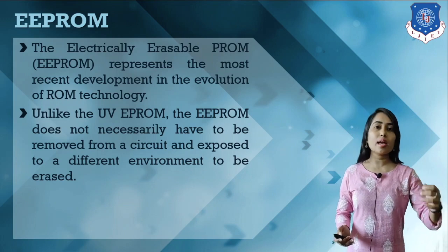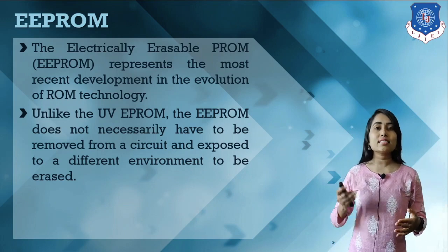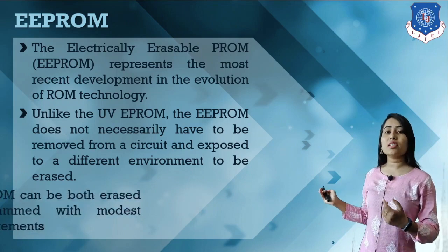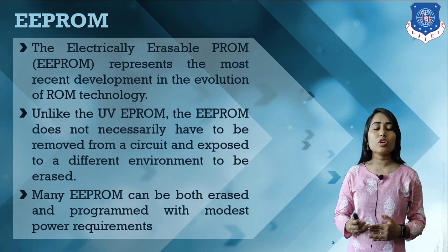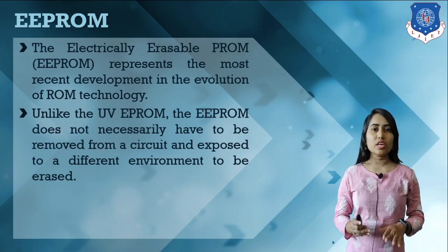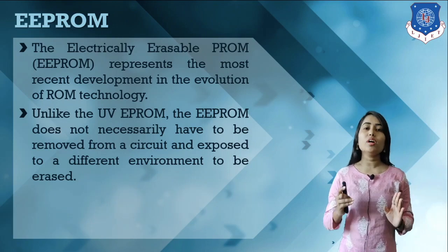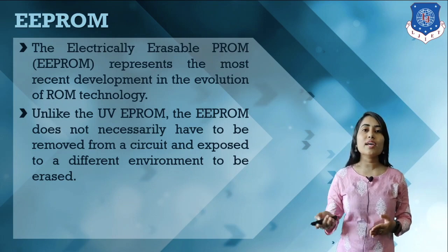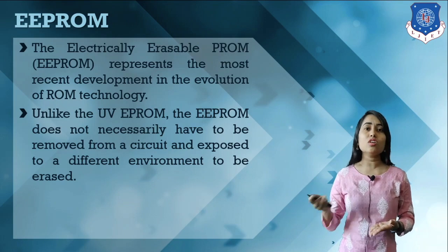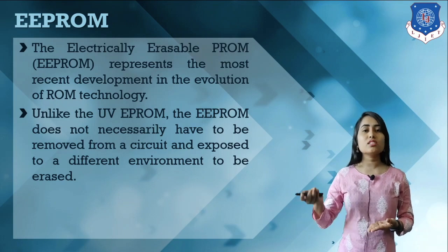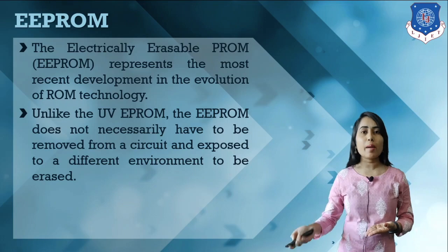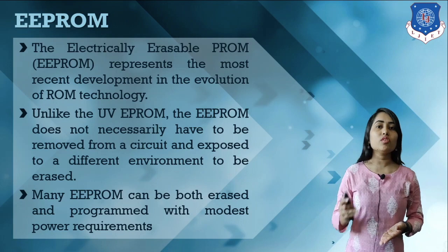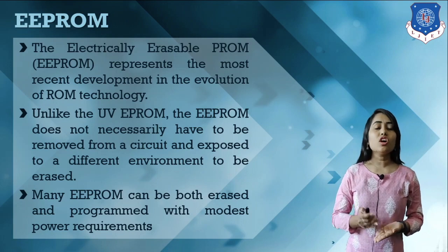So using high power we can erase the selected data, or we can erase the whole memory, and this erasing requires less time. Unlike the UV EPROM, here there is no need to place this ROM into a device to erase the data, or to place this memory into a different environment. Once the data is erased, we can reprogram it depending on the requirements.